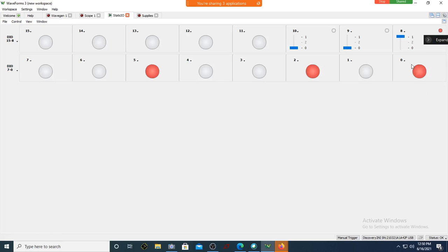Can you see? Is it a half LSB error? Instead of 36.5, we are getting 37. Whatever we represented was 36, so we underestimated by half an LSB. Now it's actually 37. Correct? Then shall we go to the next?